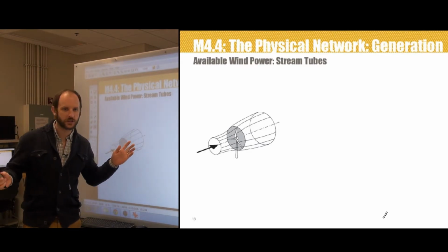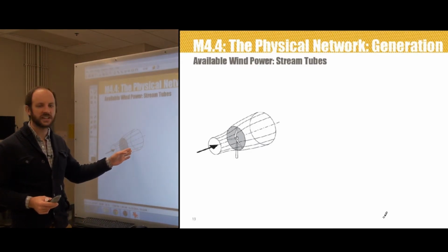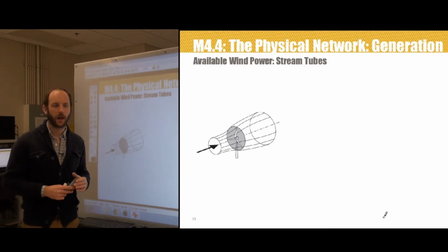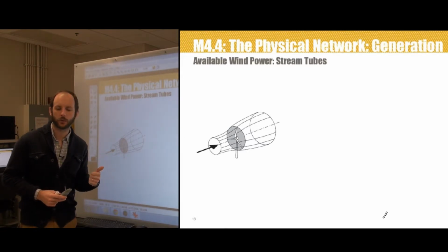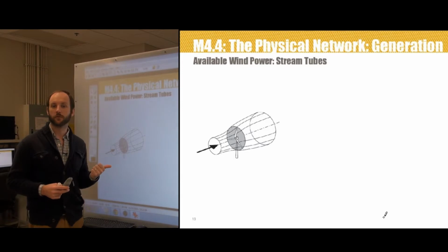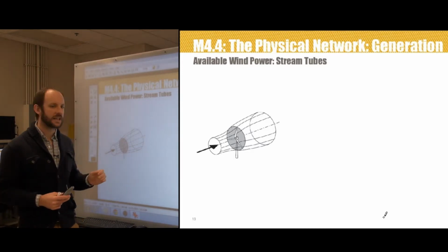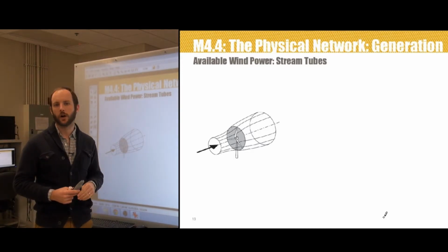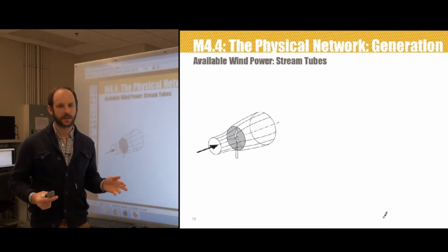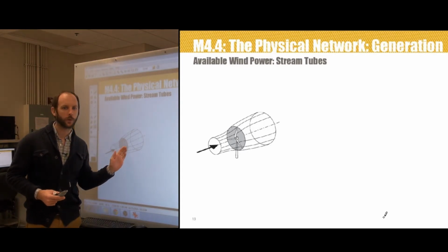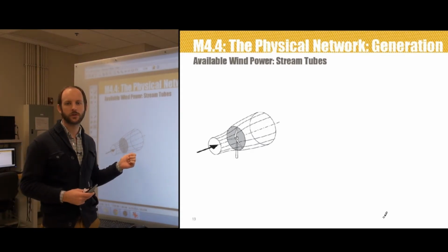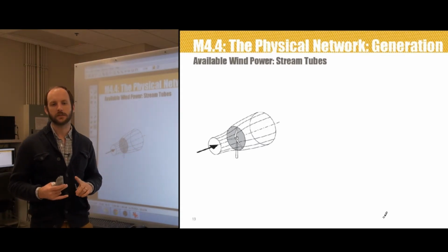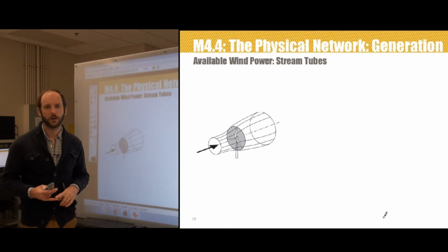If we take all the energy out of it, the kinetic energy on the lee side would have to be 0. Therefore, since it still has a mass, from the KE equals 1/2 mv squared formula, its velocity would be 0, i.e. the wind would stop moving on the lee side. This mass of air in turn would prevent any more wind from passing through the rotor, and therefore the downwind velocity of a wind turbine cannot be 0 kilometers per hour.